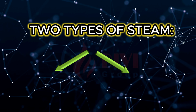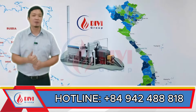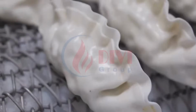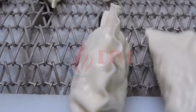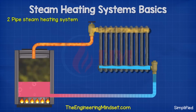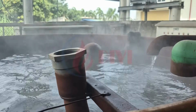Steam is typically used in two ways, direct and indirect. In direct use, steam is injected straight into the product, like steaming buns, rice paper, or cooked rice, where it mixes with the product itself. In indirect use, steam transfers its heat and then condenses back into water. This condensate is usually returned to the boiler for reuse.